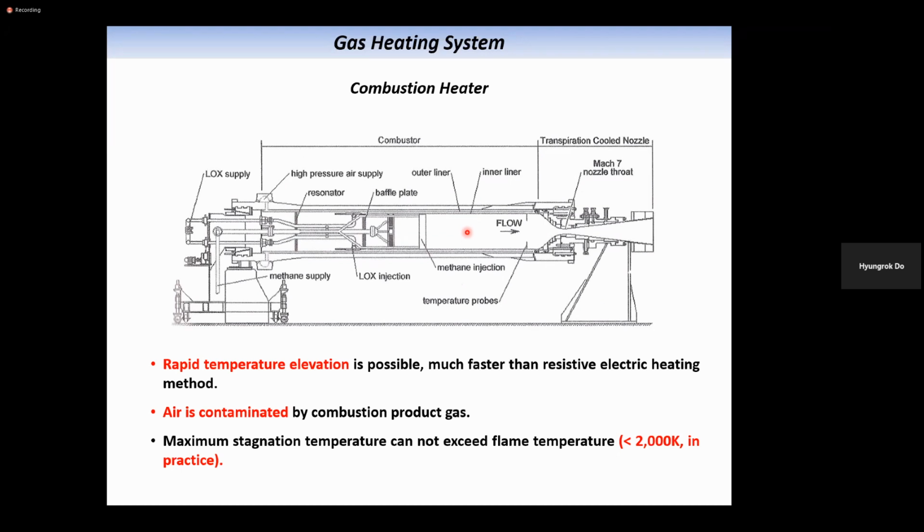Laser diagnostics cannot give you accurate information by itself in many cases. So you will have to combine the information from the sensors, and the sensor information is more accurate. So keep in mind that you are not purely or solely relying on optical diagnostics in many cases. I would say most cases. So sensor measurement is still very important. You should learn about the sensors first, and then in the worst cases, where you cannot measure with sensors, you will combine the measurement using optics or lasers.